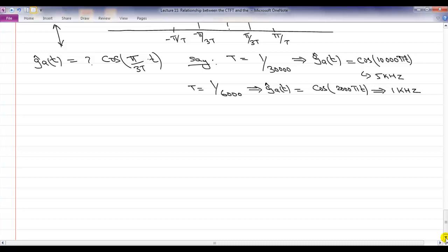So what we understand so far is, if you take your continuous time signal, we know what the discrete time signal looks like because we know the Fourier transform of the discrete time signal. If you take your discrete time signal and convert it into continuous time, we know what it will look like because we know the frequency relationship. But the reason we do sampling is because we want to do processing. So the idea is, how do we use the information that we have gained so far for processing of continuous time signals using a DSP system?